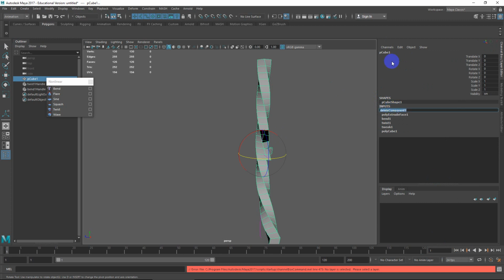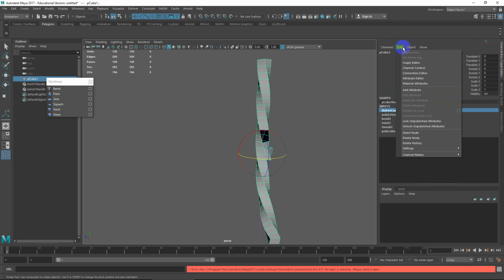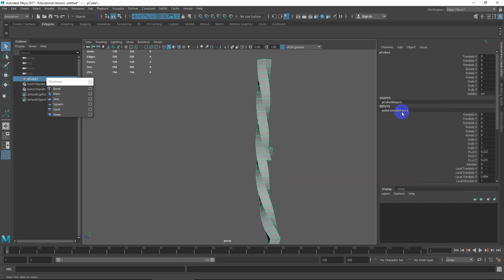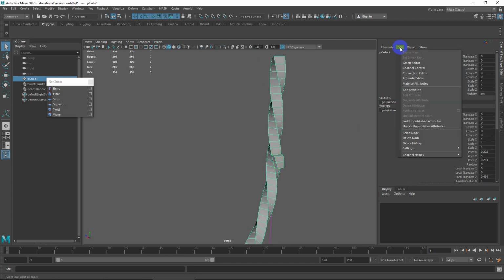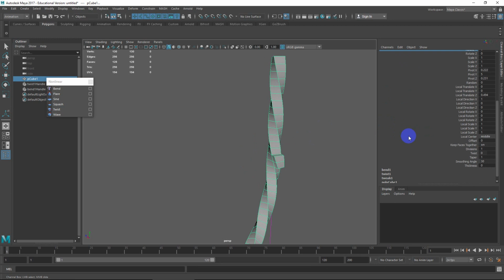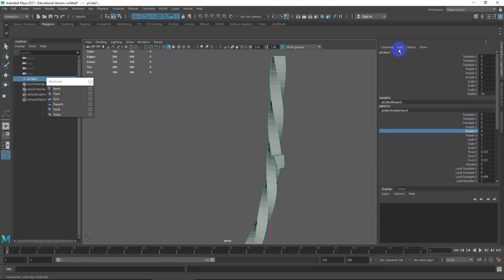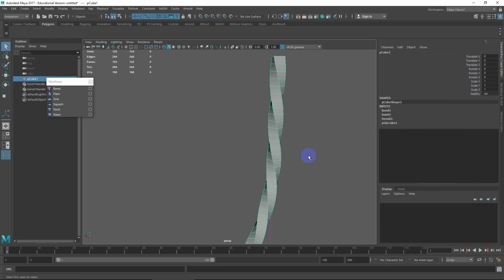A lot of times when I do my basic editing, yeah, we can delete these nodes, by the way. So if you want to undo the edits, you can select the node. In this case, I had an extrude face node, so I'm going to grab that node. There we go. And go to edits, delete node, and that can take the edit out. So I can go back and put the edit where I need to put it.